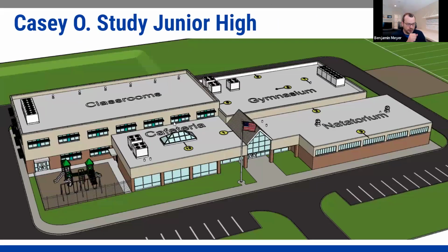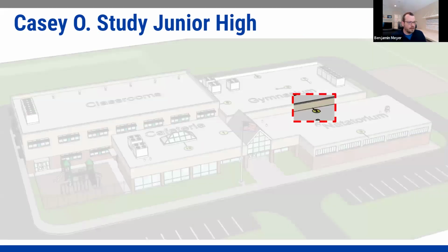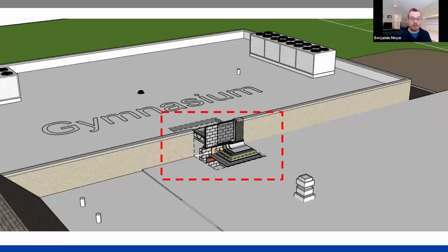All right, we'll go through our third condition. And really, this one's the trickiest of all, and it connects between the natatorium and the gym. So it's an exterior wall connecting two different interior condition spaces. Herman talked right at the first slide, I think, about when we have an interior space with multiple conditions, how do we separate them? This is one of those cases where you really don't want your natatorium space flowing down the hallway into all the other conditions. It really wants to be contained, so you can manage it and also manage the comfort in your gymnasium and the others. So this one, I promise complexity.